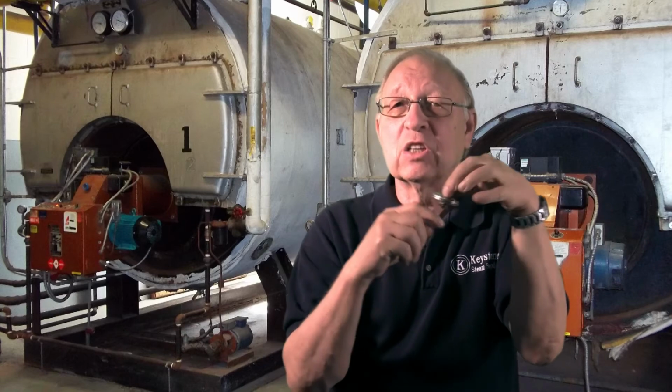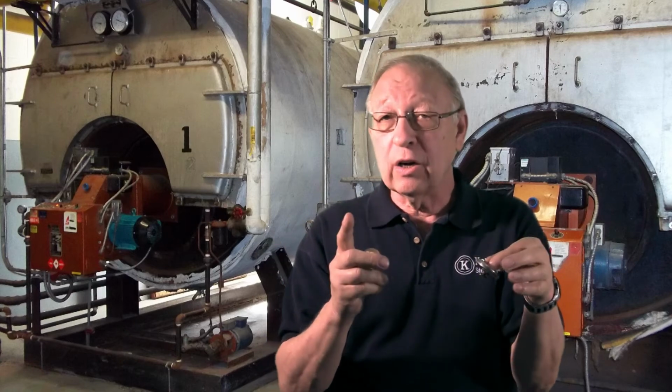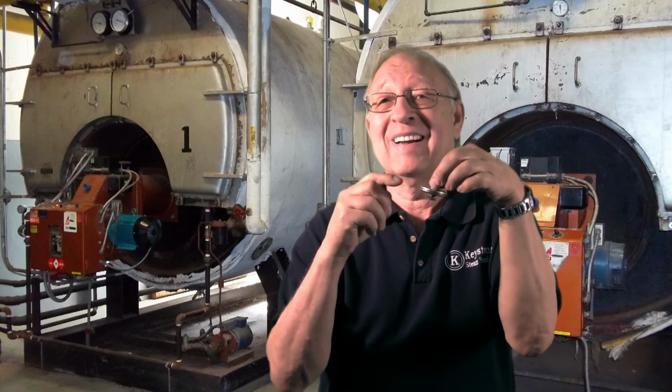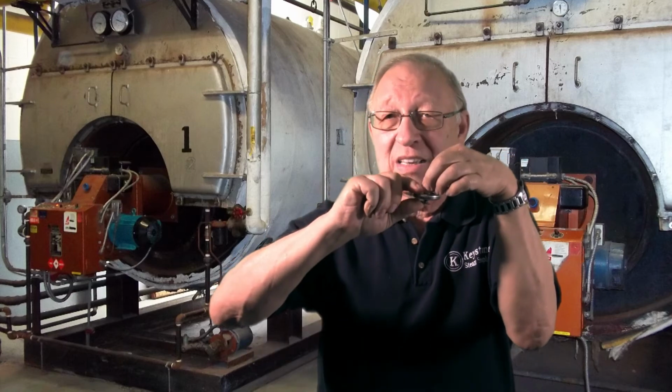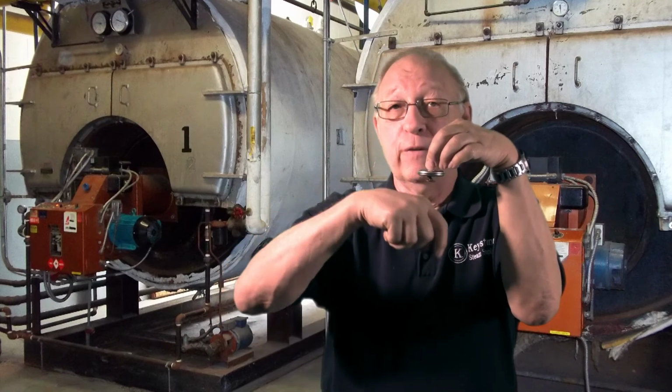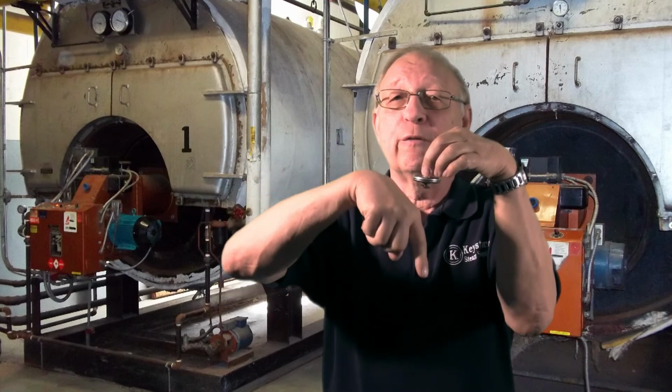Once that steam has expended its energy, whether it's to heat a radiator or turn a turbine, and condenses into water, that water now surrounds the bellows, and the steam inside the bellows condenses into water, contracting the bellows. This backs the plug away from the seat and opens the orifice in the bottom of the trap, allowing the condensate to flow into the return piping system and thus making its way back to the boiler where once again it turns into steam and the cycle repeats. And that's how a thermostatic trap operates.